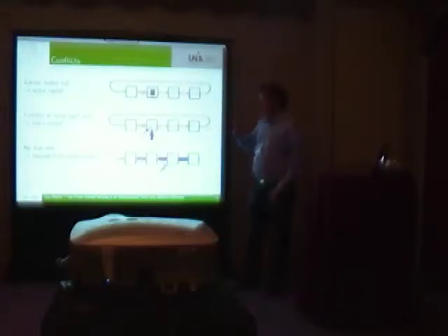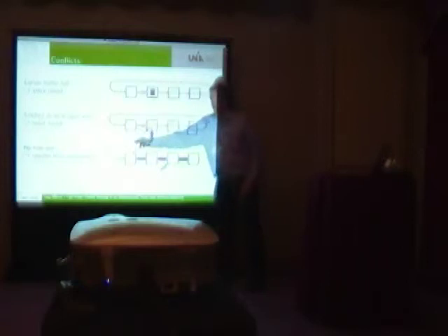And when it gets this signal, it only uses every other free slot that it gets. So if it gets 1 slot, it uses this one, the next one it lets go free, so the next node can use it, and so on. And if this one does not get a free slot, it can even demand one from the node before it, and so on. So this is a cascade to ask for a free slot.